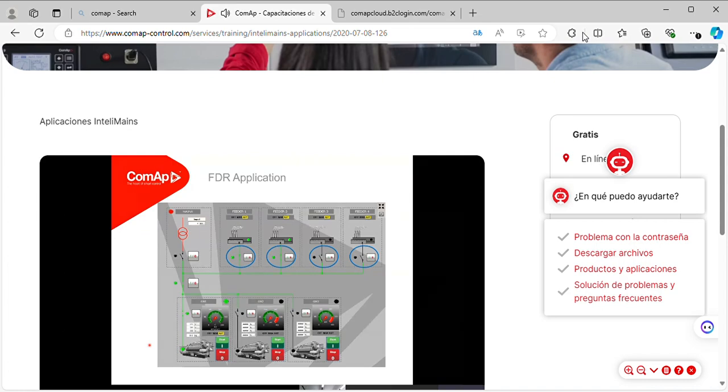Based on the communication with the genset controllers, it can see how many gensets are available at a given point of time and how much active reserve there is, and based on that it will automatically isolate the non-priority feeders and keep feeding the priority ones. That's a pretty straightforward application, and you can also load shed at different levels using the feeder controllers. So that's the fourth example of InteliMains controller.